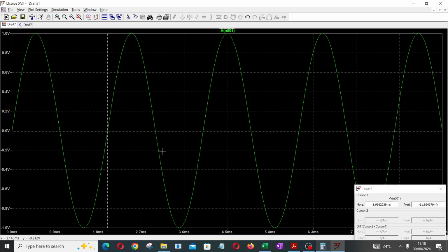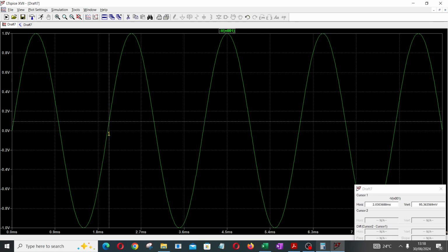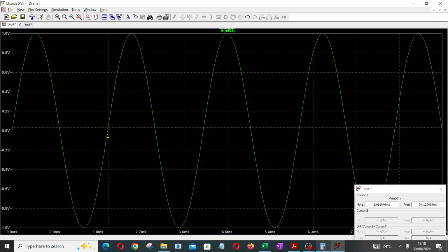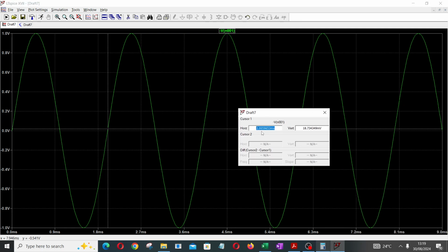So at this point, what is the value? It's almost 2 seconds. No, 2 milliseconds. That's at the point where you get 1 complete oscillation. It's 2 milliseconds. It's already here. You can bring out this guy to see the time. That's 2.005 approximately. That's almost 2 milliseconds.